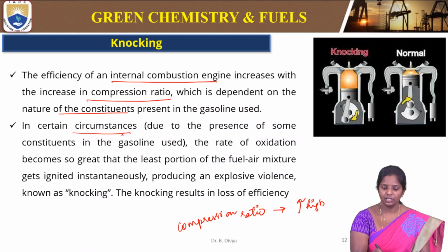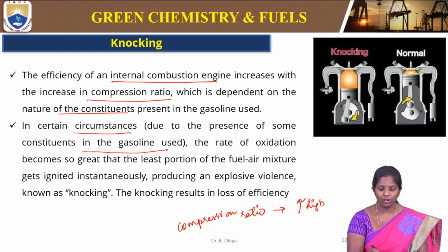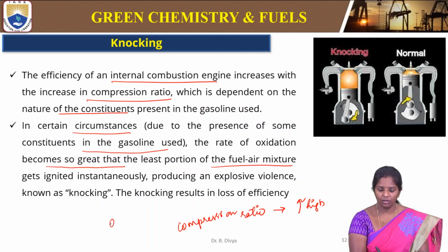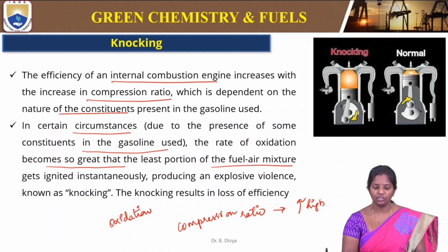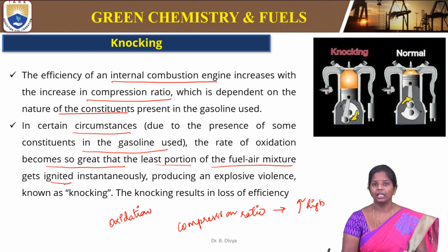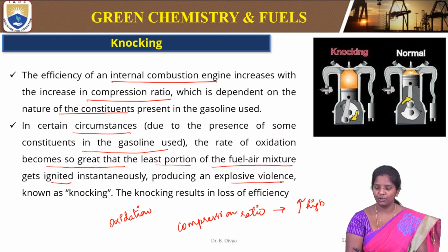In certain circumstances, due to the presence of some constituents in the gasoline used, the rate of oxidation becomes so great that a very small portion of the fuel air mixture gets ignited instantaneously, producing an explosive violence.